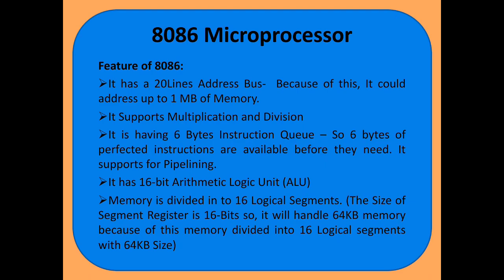Here it has a 16-bit ALU, and the memory is divided into 16 logical segments, where these 16 logical segments are divided equally among 4 different segments. That means we have 4 segments: code segment, data segment, extra segment, stack segment. All these memory segments are used equally.